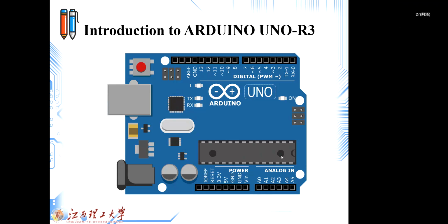If you want to remove this IC, you can simply do it with the DIP one. But for the SMD parts, it's difficult to disconnect it from the board. In other words, if anything happens to your board and IC, it's difficult to change the IC. But for the DIP one, you can remove the IC and use a new one.